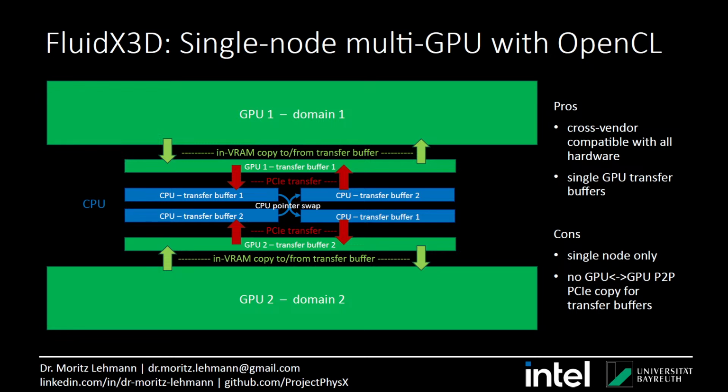And when you run it, if there are enough GPUs of the same name, they will automatically get assigned to the domains, or you can also manually specify a list of GPUs if they are unequal GPUs. So say you want to run it on GPUs with ID 0, 5, 6, and 7, you can specify it for 4 domains and they will get assigned.